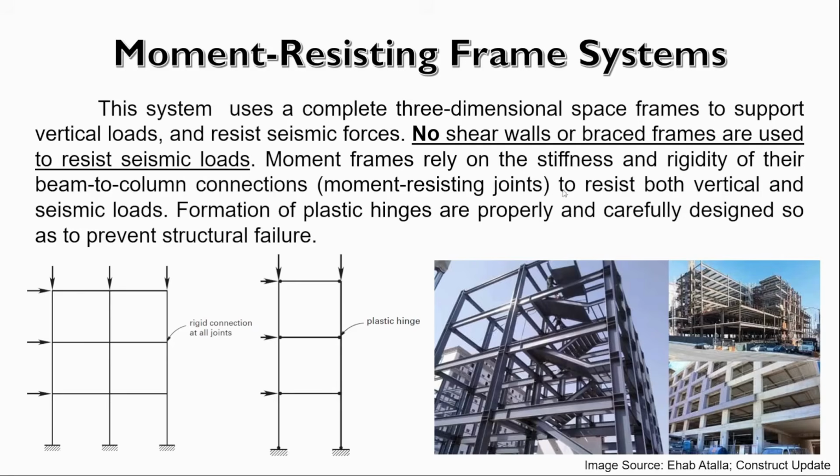So remember, if you are designing a structure without shear walls or brace frames, remember that moment resisting frame systems have what we call beam to column connections, and we must carefully and properly design where the plastic hinges should form.